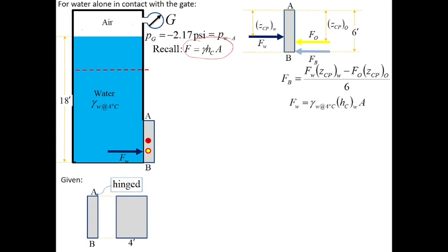Imaginary liquid surface. Okay? Imaginary free liquid surface. So in this case, at this point, the pressure is equal to 0, because as we go down, the pressure will increase. So from negative, there will come a time that it will become 0. And this is now our imaginary free liquid surface, wherein the pressure is 0.